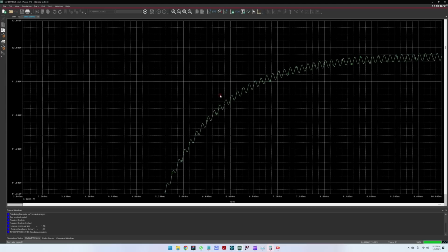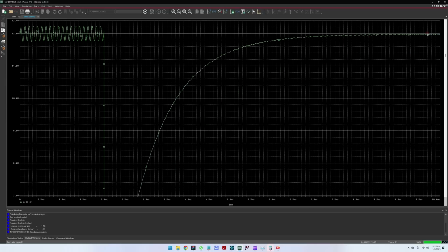Okay, and this is how we use the capacitors to filter. We want here on the output clean signals, very little ripple, stable voltage levels, and on the input here being a noisy input, yeah, we need to filter this. Always filter the signal to be as clean as possible.